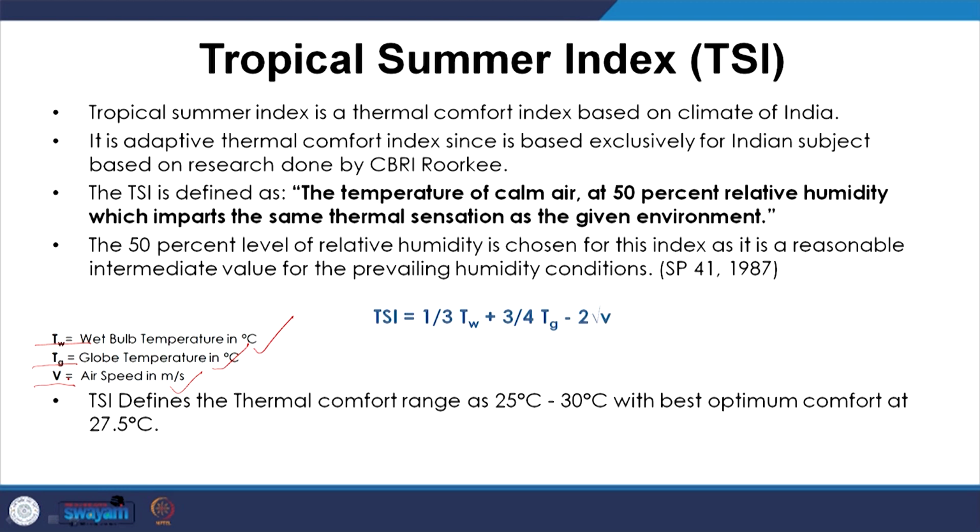So, through this we are taking into account the adaptive thermal comfort. However, no specific consideration for the clothing value and the metabolic rate has been taken through the tropical summer index. Yet, because the tropical summer index is based on the study of Indian subjects, it is very close to the experience of tropical Indian subjects as far as thermal comfort is concerned.